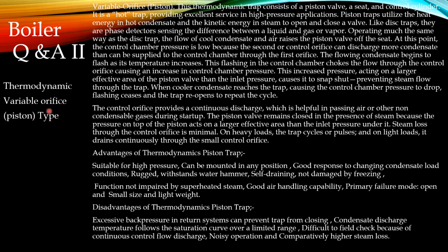Next type is the thermodynamic variable orifice or piston type. This thermodynamic trap consists of a piston valve, a seat, and a control cylinder. It is a hot trap providing excellent service in high pressure applications. Piston traps utilize the heat energy in hot condensate and the kinetic energy in the steam to open and close a valve. Like disc traps, they are phase detectors, sensing the difference between a liquid and gas or vapor, operating much the same way as the disc trap works.